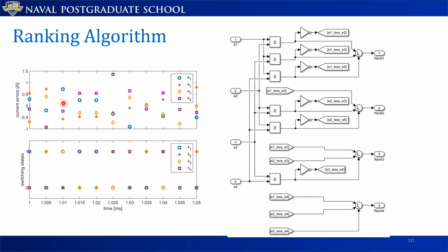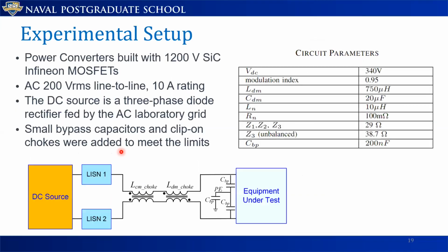Of course, you have some small errors, and everybody working on common mode knows that sometimes there is a penalty to pay for differential mode. You can see, for example, here that in the end, phase 2 really would like to switch low, but we don't let it because we have to have 2 high and 2 low at any given time. So it is important that we verify in the lab also the differential mode performance of this converter because of the compromise we make.